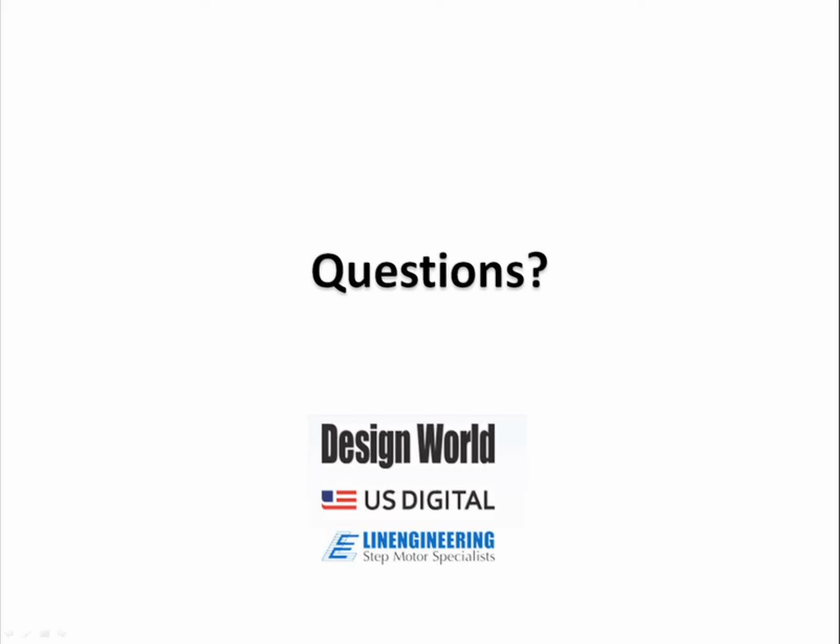All right, and then I don't know if this is related to a slide. There's a question just for clarification on what the P and I coefficients are. Does that make sense? I don't think it was in one of the slides, but I think they are talking about PID control. Basically, the P stands for proportional and I is integral, and this is one of the most common ways to use feedback in a control system, basically closed-loop control using a motor and encoder and a controller that does this PID feedback. It's basically adjusting the error, actual position versus the desired position.